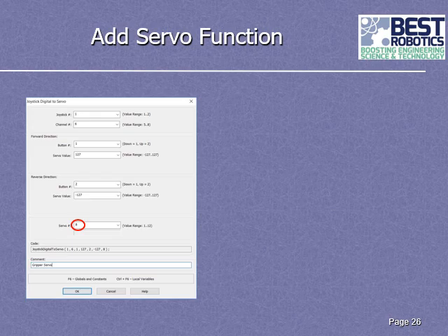Again, you have to pick a motor port, so just pick one that you haven't used before. One good rule of thumb is you have ports 2, 3, 4, 5, 6, 7, 8, 9, so you have about 8 ports you can use. Try to spread them out amongst the first 4 and the second 4. It's kind of a power management thing. I'm not going to go into the details of that, but if you can, especially with the bigger items like the motors, keep them on different sets of 4 just for power management. So in this case, we're picking port 8.